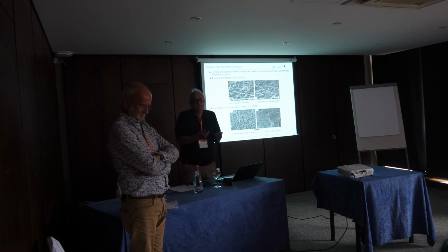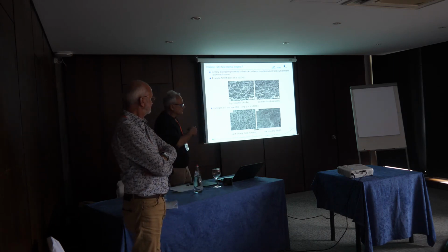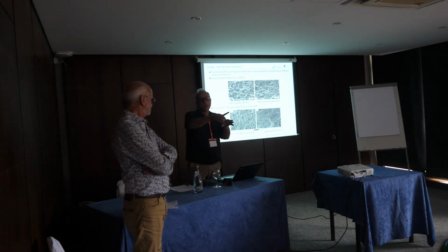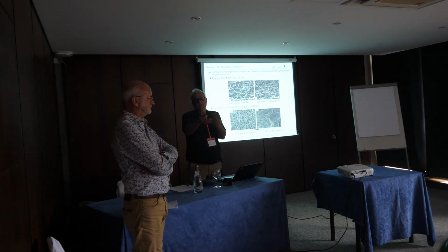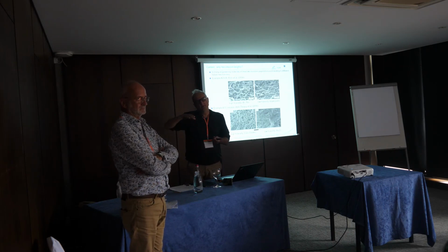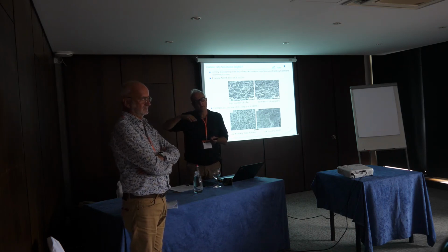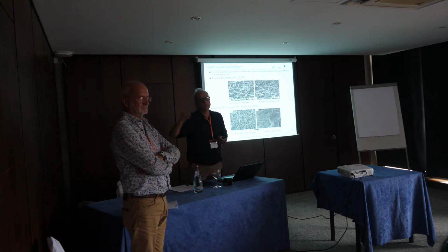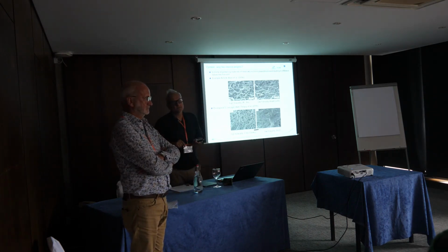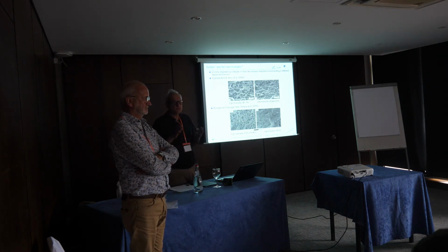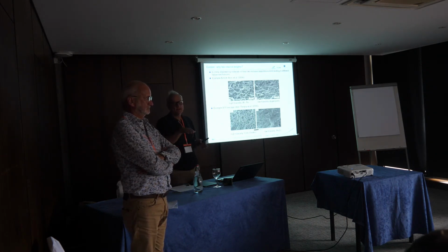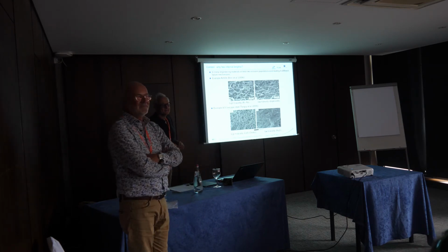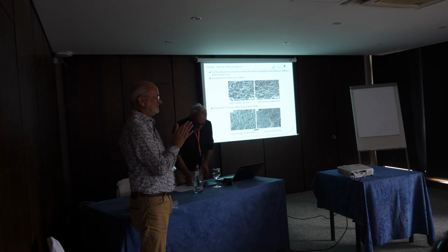This possibly can be used to model this flat to slant transition, which is a more complex thing. It's basically the same thing, because when you have cup-cone fracture, triaxiality decreases from the center when the crack propagates towards the outside surface. So hopefully in 3D, we should be able to get flat to slant transition. Okay, thank you. But it's difficult. Okay, thanks again.